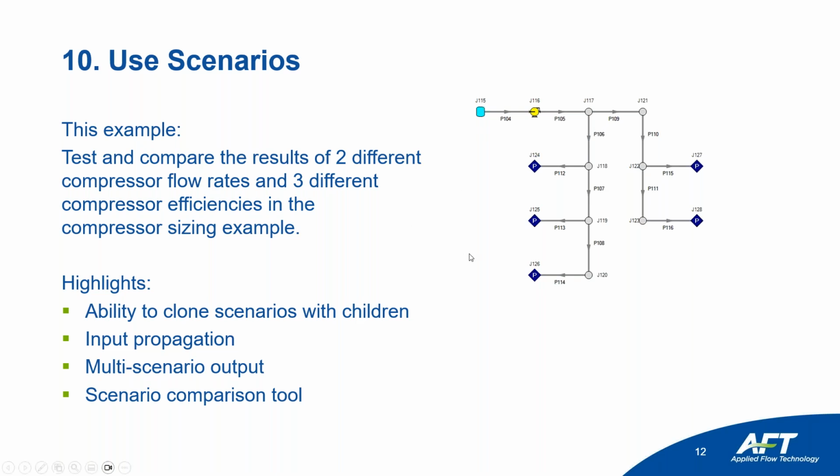So we're going back to our compressor sizing example, and let's say we wanted to test 2 different flow rates of our compressor at 3 different compressor efficiencies. So a total of 6 different models. You can do that all within the same model using different scenarios, and you can vary all of those, have propagation happen, and I'll show you what that looks like.